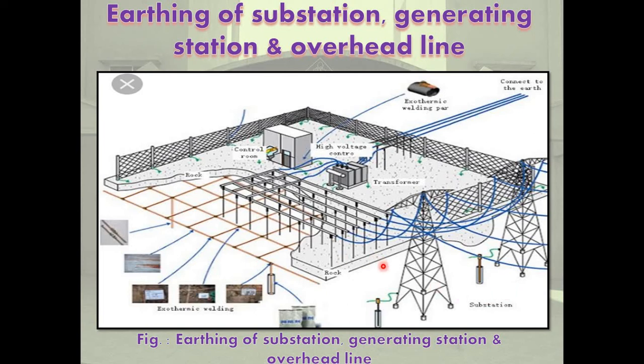The lightning strokes are intercepted by overhead transmission lines or towers and distribution line poles, outdoor substations, tall buildings, etc. The direct stroke produces a voltage surge in the transmission line and distribution line that causes flashover and failures of line insulators and terminal substation equipment, generating station equipment, etc. Extensive damage, fires and destruction by heat, loss of life and property are caused by lightning strokes.